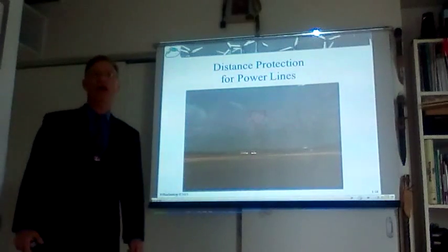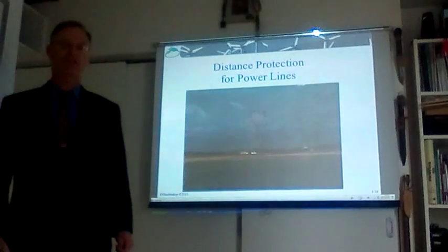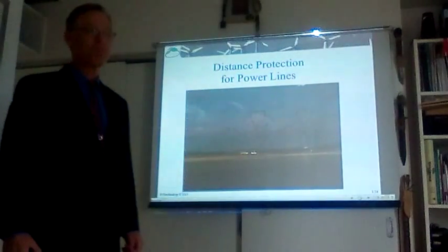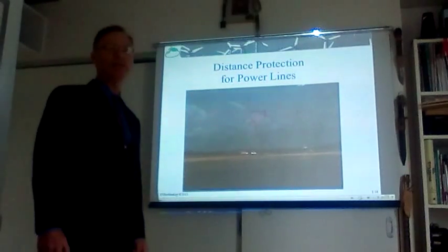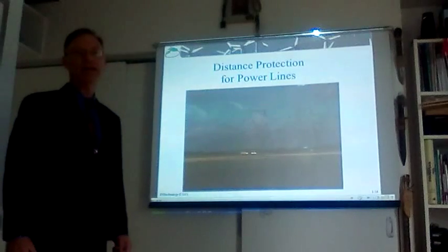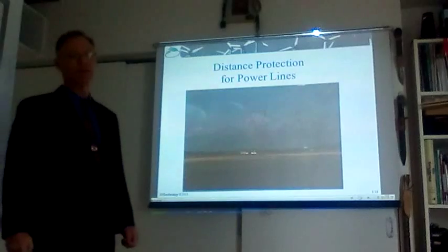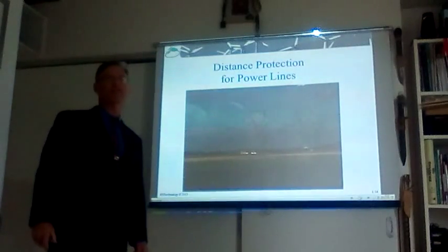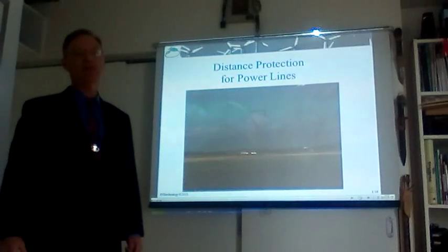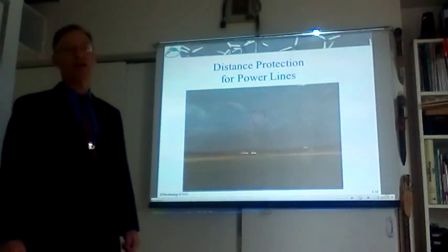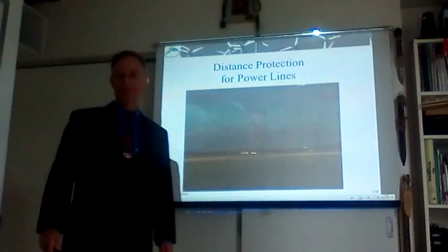Distance protection is applied only to utility transmission lines, and traditionally it will never be applied beyond 50 kV. Since the standard around 50 kV is 63 kV and up, you will find distance protection only above 63 kV lines.